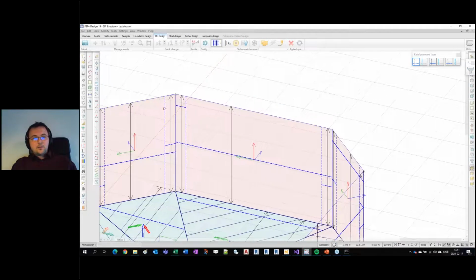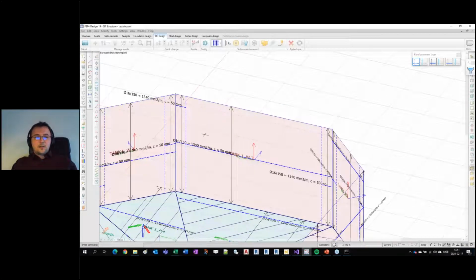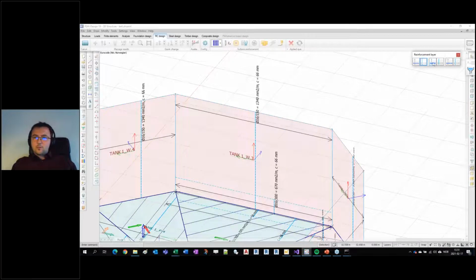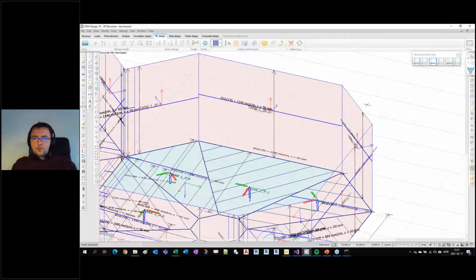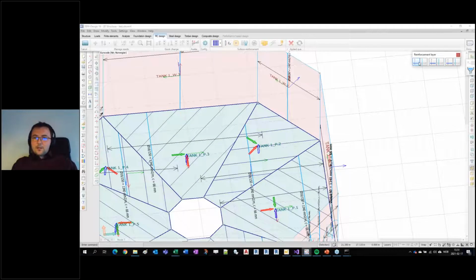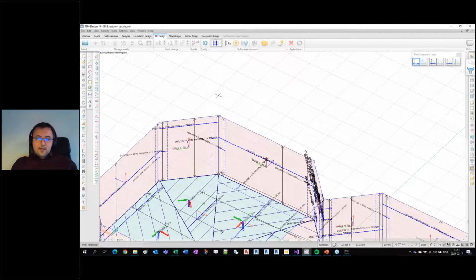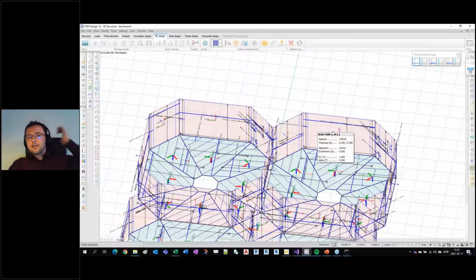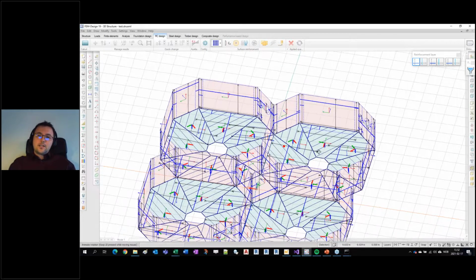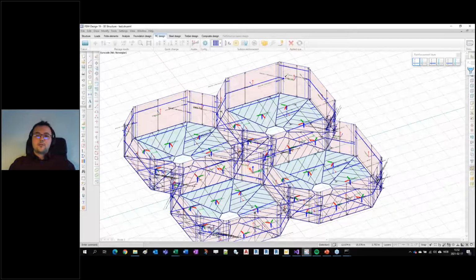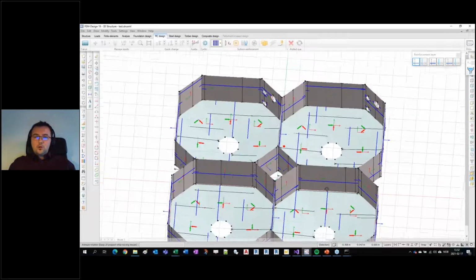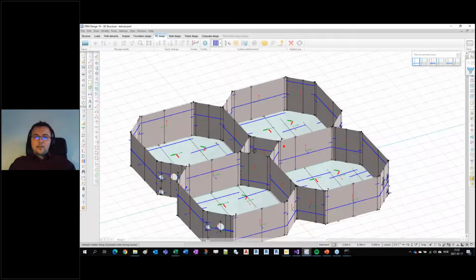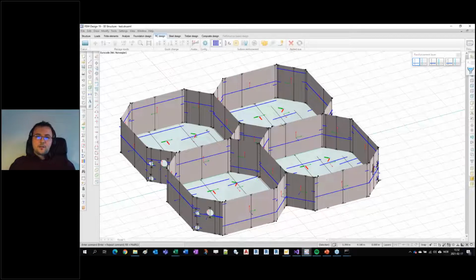So usually, in the horizontal direction on the inner side, one has additional horizontal reinforcement in walls, additional vertical reinforcement in the vertical direction, and also additional reinforcement in plates. So developing the application made it possible to have more intuitive filtering of elements. It's relatively easy, for example, to extract all outer walls, or all inner walls. Then it will be using the user interface in FemDesign.